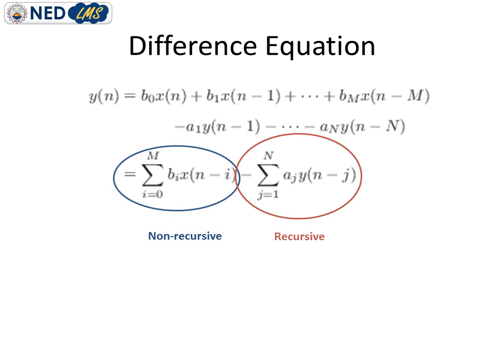But if we talk about a finite impulse response filter, then you can easily say that for an FIR filter this recursive part is equal to 0, because there is no feedback, no previous output sample fed back to the input side of the FIR system.